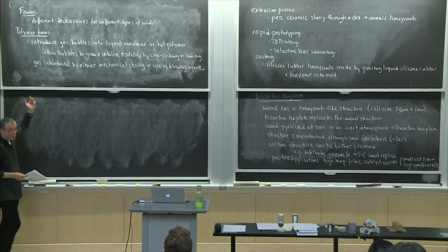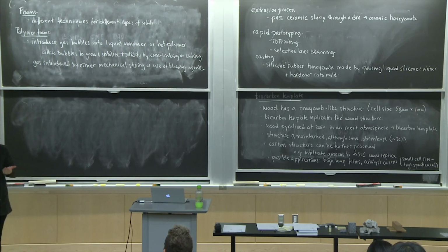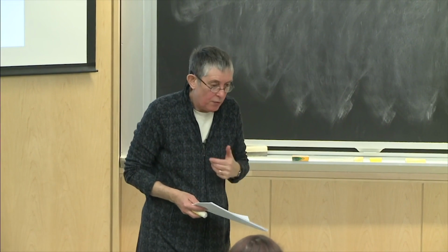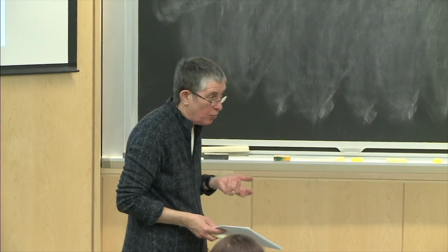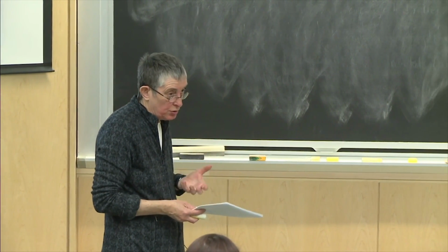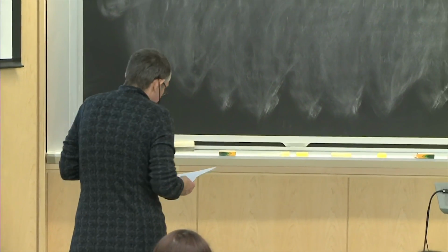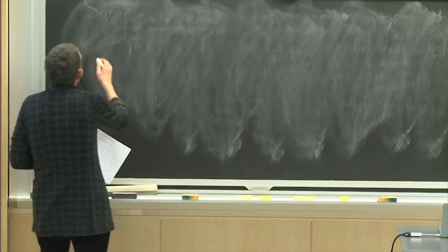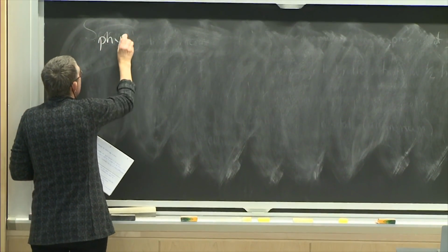So the blowing agents are divided into physical and chemical blowing agents. And the physical ones, they force the gas into solution under high pressure, and then you reduce the pressure and the gas bubbles expand. So you can use physical blowing agents.